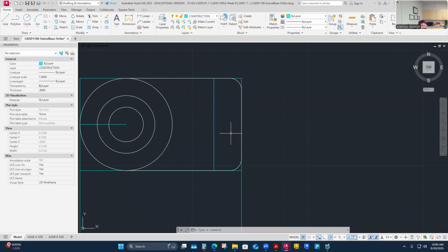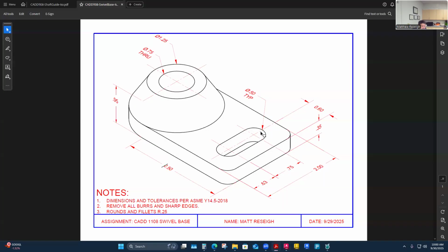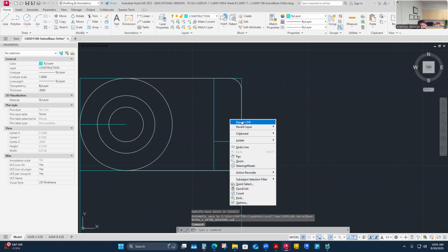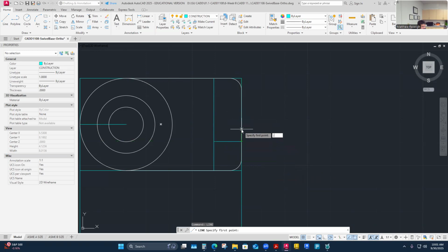I need 2 circles though, so I need a circle. And what are the diameters of that? They are a 1/2 inch diameter, so these are like a 1/4 inch radius. So I think I'm just going to cursor up on that line 0.63 and put a, yeah, I think so. 0.63 and then 0.75. Technically, I could come over here with my construction line and come up here, 0.63, cursor over, and then I'm just going to snap it to that line. That's the endpoint of one circle. I might repeat that up from here, should be 0.75 and then over. So those two are our center of circle.